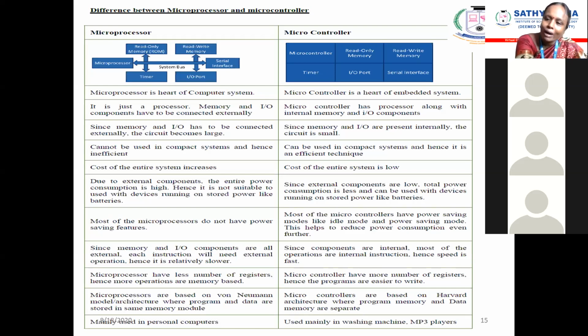Can you understand? In a microprocessor, due to the small number of registers, we have to use so many logics to move from accumulator to B, and from there only we have to save. Those problems will arise. But in a microcontroller, we don't have such a problem. We have some bank registers, nearly 32 bank registers. Apart from that, we have the accumulator, B register and all.